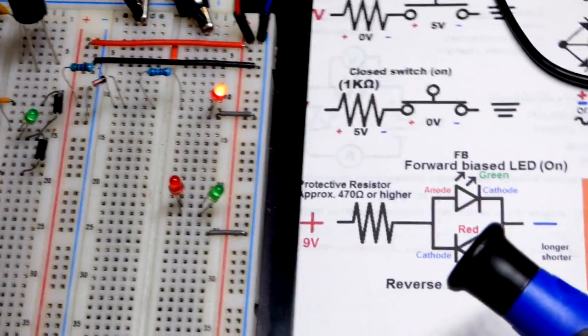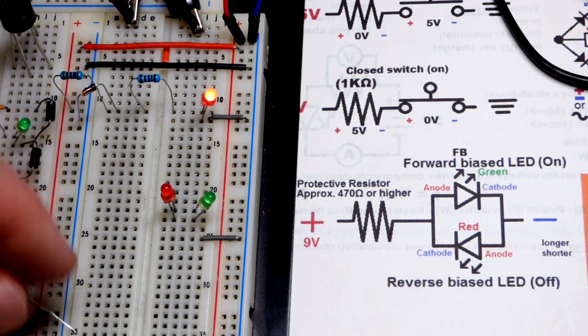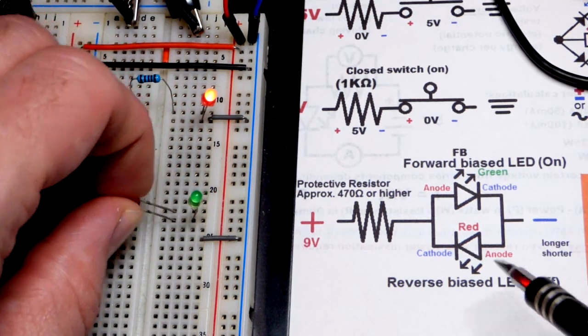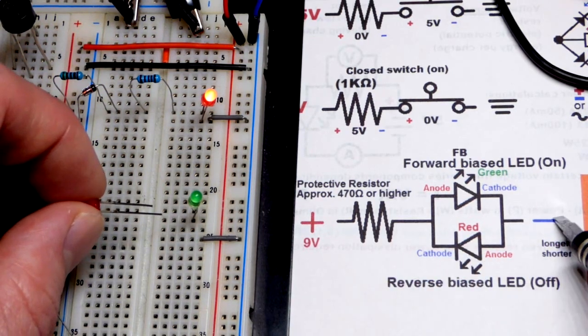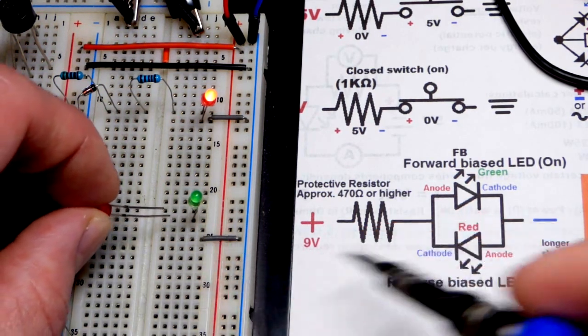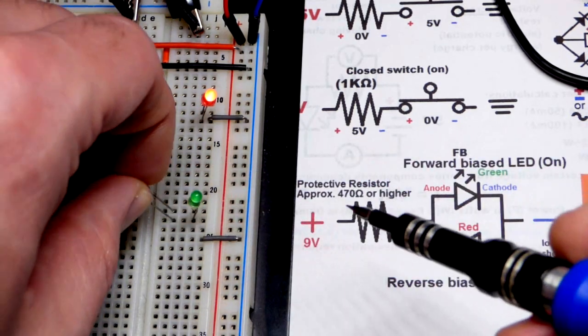So now next, I think we will go to the polarity indicator, and we got a couple LEDs down here, and so we're going to swap which direction the power is, but we're going to grab a 1 kilo ohm resistor, and so we got the red LED. I usually work my way down more negative, so I'm going to put the long lead, the anode, down right there. It actually doesn't really matter. Short lead cathode is up 1 row.